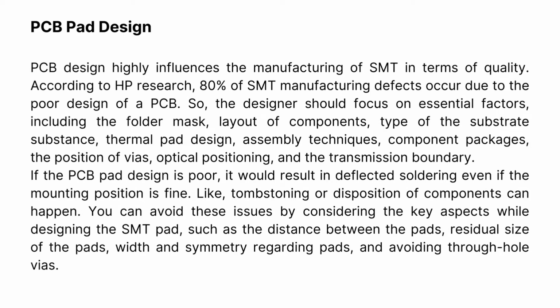PCB pad design. PCB design highly influences the manufacturing of SMT in terms of quality. According to HP research, 80% of SMT manufacturing defects occur due to the poor design of a PCB. So, the designer should focus on essential factors, including the solder mask, layout of components, type of the substrate substance, thermal pad design, assembly techniques, component packages, the position of vias, optical positioning, and the transmission boundary.